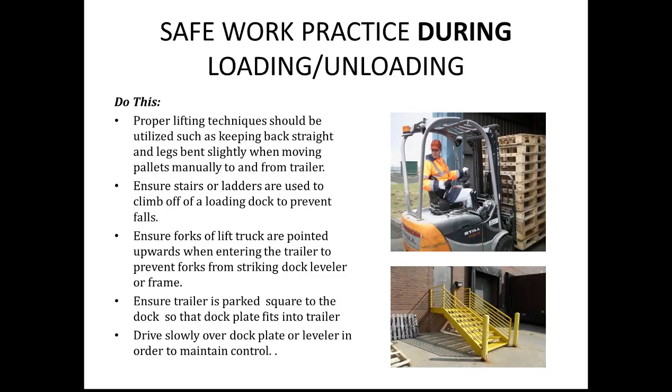Another thing to do while you're unloading trailers is to make sure you raise your forks upwards while you're entering and going over the dock leveler, so that they don't catch the raised lip or the frame of the dock leveler when you're entering the trailer. You also want to ask any operators that are going onto the trailer to make sure the trailer's square and that the dock plate fits properly onto the trailer.